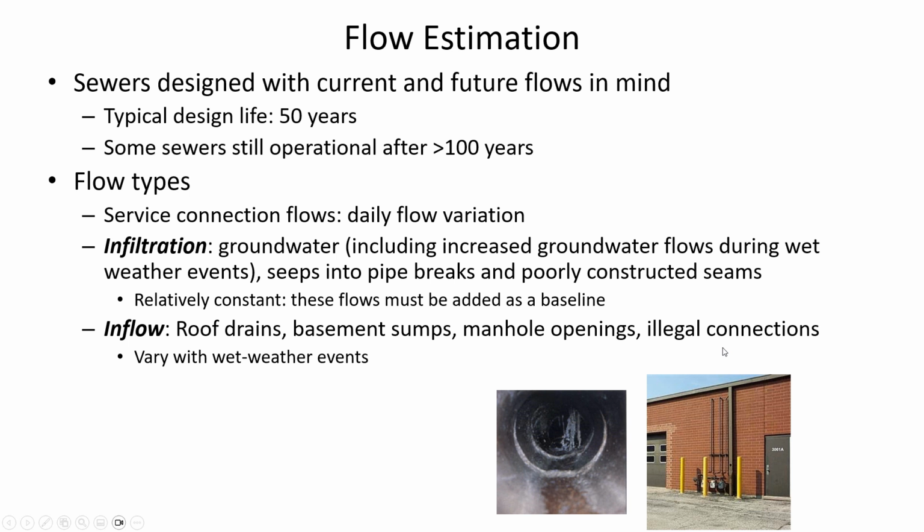People don't want it discharging right next to their foundation, but as long as they just have the spout discharging a few feet away from the foundation, then it shouldn't cause any risk to the structure itself. And then here's a picture taken from an inspection camera, where you could see water seeping in from cracks in the pipe. So that would be an illustration of infiltration.